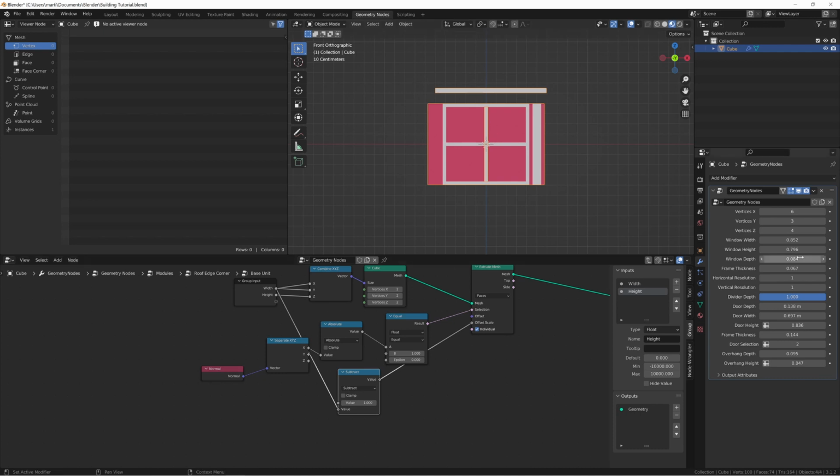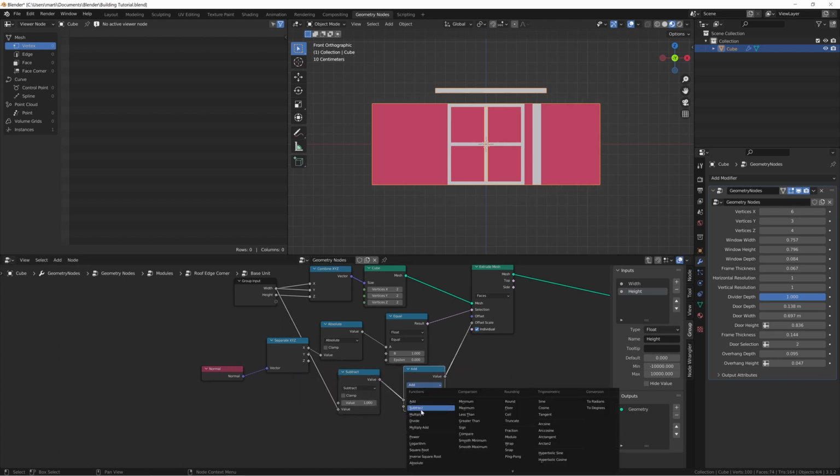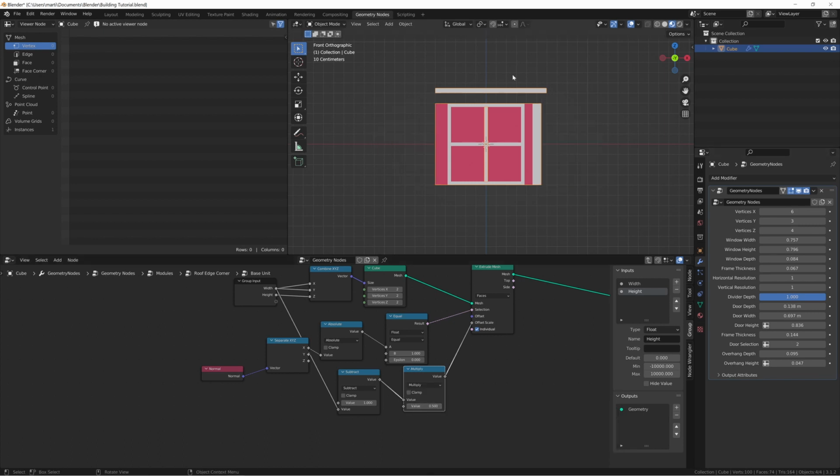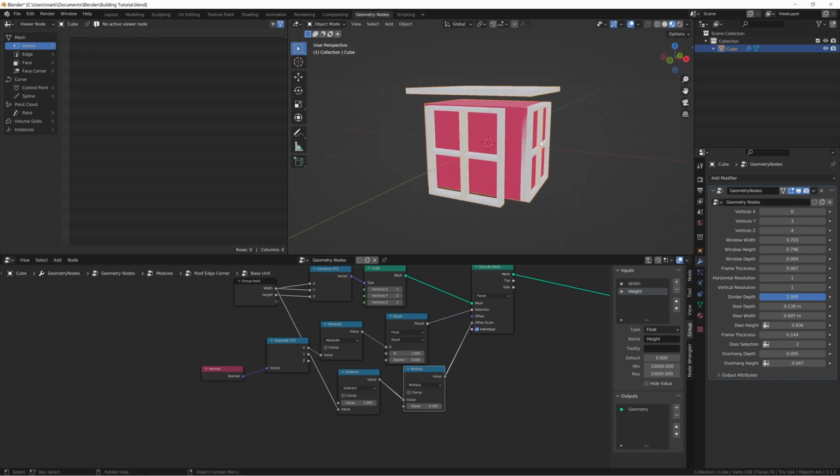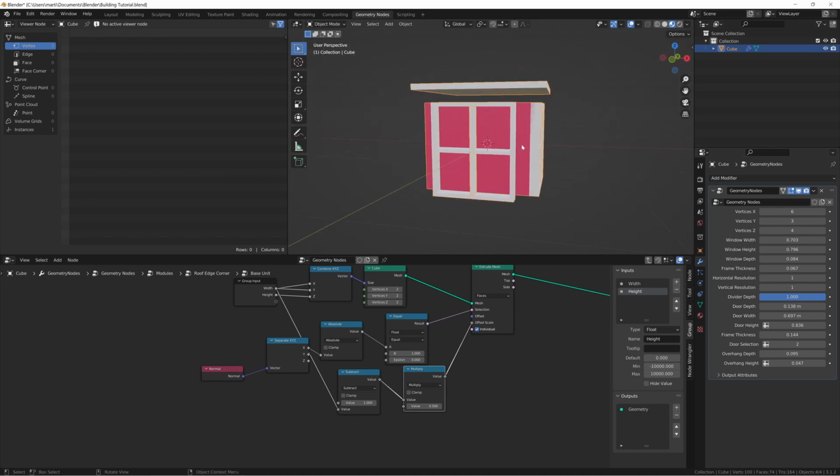And that should make it so that it will always be procedurally controlled by the window width, but you can see that it's still not right. And that's just because it's extruding by the difference between the width and 1 on both sides, but we only wanted to do the equivalent of extruding it on one side. So we'll just take that and multiply it by 0.5, and that will get us to the exact right value all the time, no matter what the window width is. You see as it's going in and out like that, it is continuing to work. So good, that gets us our x-axis, or how wide it is along that axis.